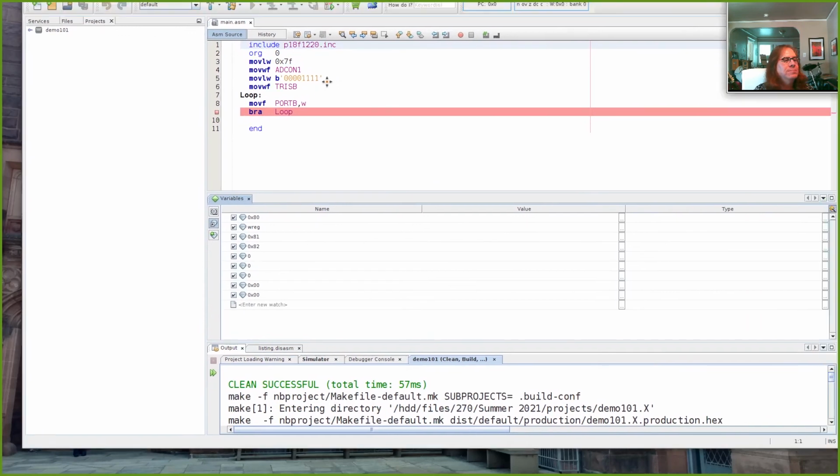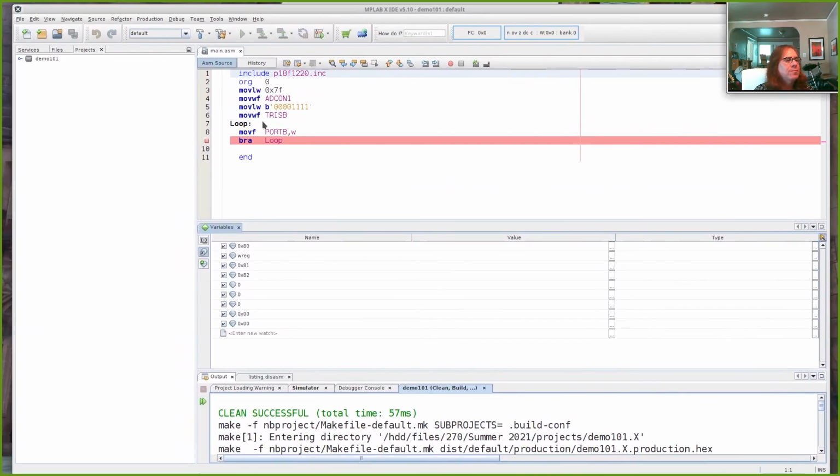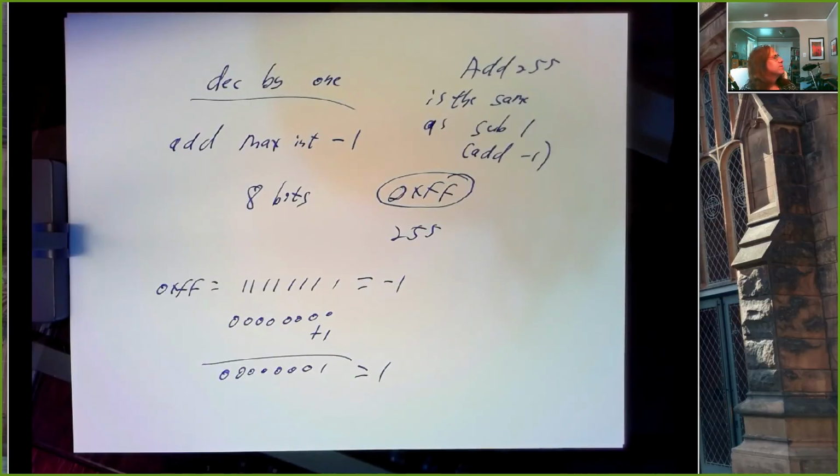Speaking of trying to break things, I actually was trying to set port A so that I could use more than one bit for my second experiment. I tried manipulating what I believe is the value of TRISA, the literal right above it, and seeing if that would do it, but I guess that's just for direction only. So we're going to talk about TRISA and port A today.